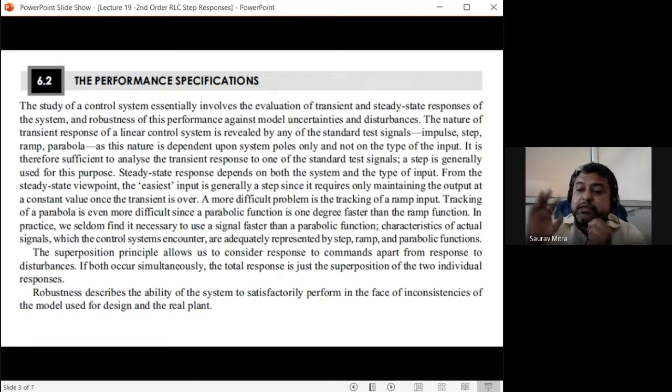So ये तीन चीज तुमको एकदम clearly तुम्हारे दिमाग में रहना चाहिए. First thing is, if gain is more, stability is less. Correct. Second thing, if zeta is more, damping is more, stability is more. Okay, so relationship between damping and stability is directly proportional. Relationship between gain and stability is inverse. Okay, so ये एक line लिख के रखो, that zeta is directly proportional to stability. More is the stability, more is the zeta, or otherwise we can say vice versa.